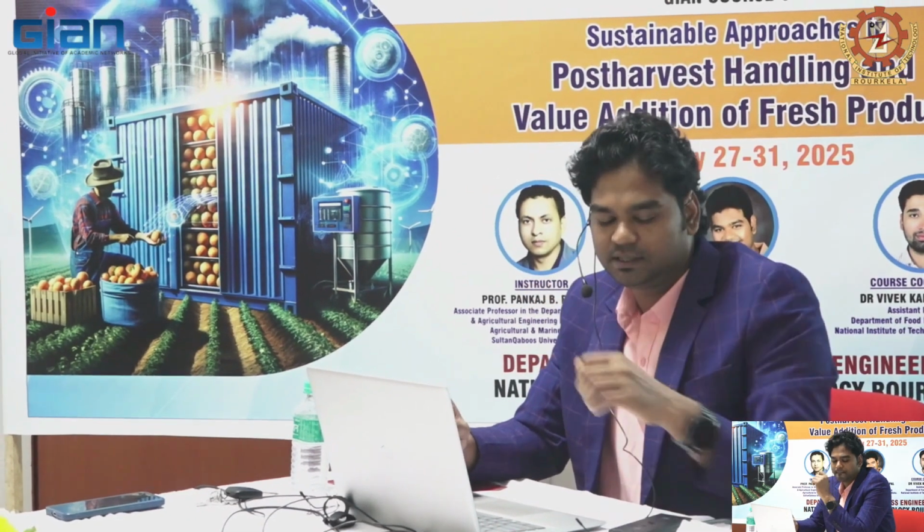Good afternoon, sir. My question is, at what temperature range is this cold plasma process carried out? It is atmospheric temperature only. If you generate plasma and expose it to a surface for 3 minutes, 5 minutes, the temperature may increase, if the initial temperature is 30, it may go to 32, not more than that. If we are continuously exposing to plasma, the surface temperature may increase by 2 to 3 degrees Celsius. That's it.